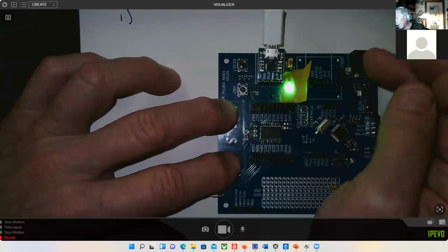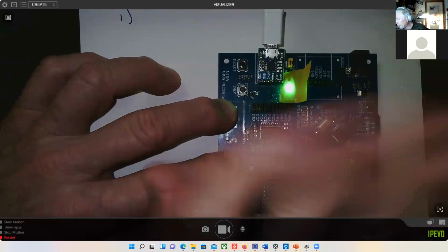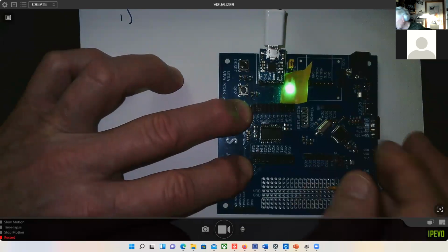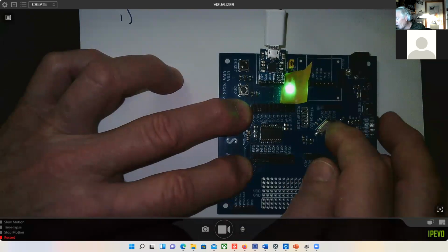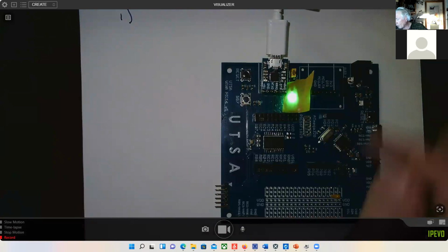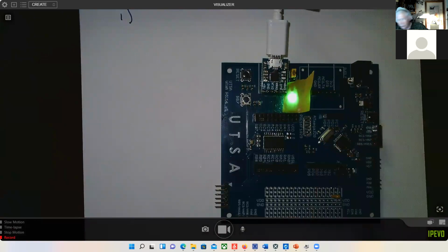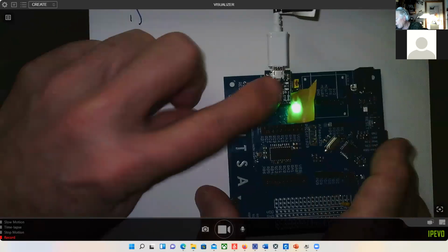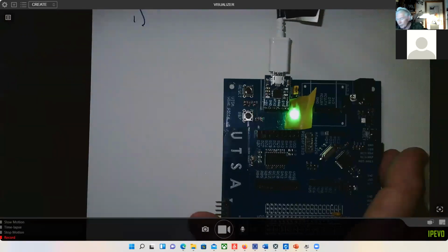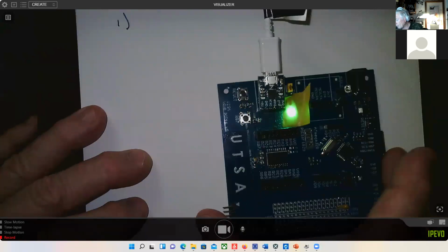So the battery can only power the board at 3 volts, which is fine for the PIC, but it might be a problem for the Arduino IDE. That chip will run on that, but a lot of the devices that we might interface are going to require 5 volts. So probably that's one mod I'm going to make on the next board. I'll put on a 3 and a 5 volt regulator, which is what we used to do on the old Viva board, but we thought maybe we could get by without it. A lot of students last year powered their boards with the CP2102 anyway and never used the battery. I'm still pulling my hair out about the best way to power the board.